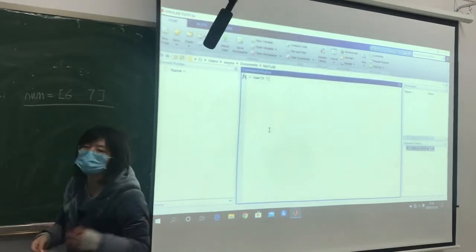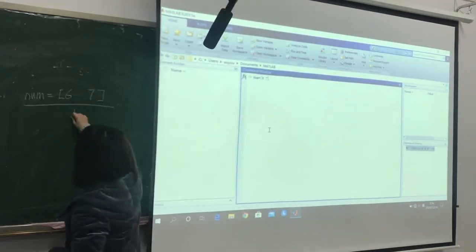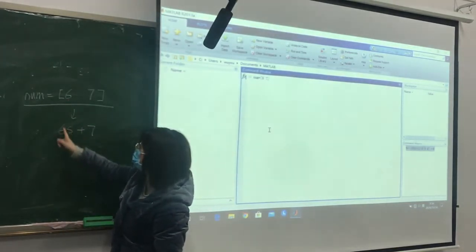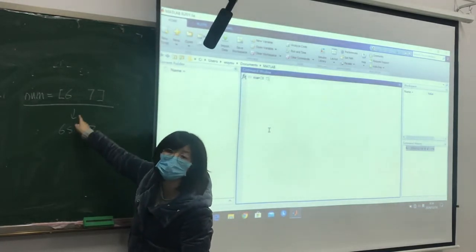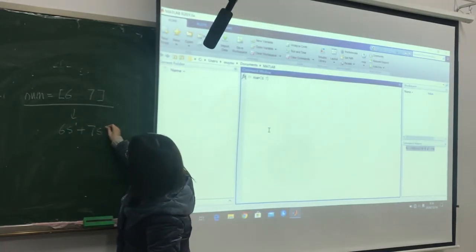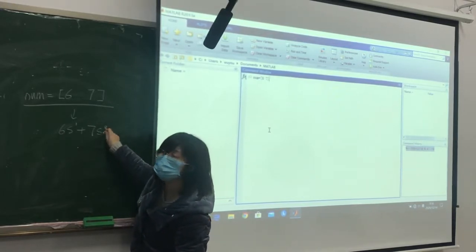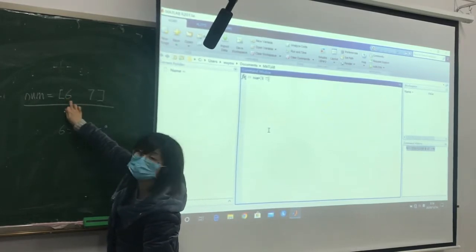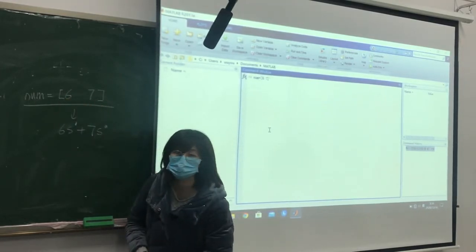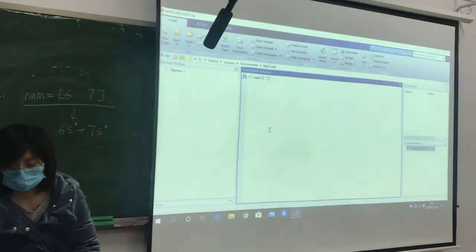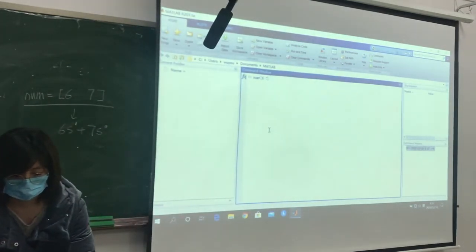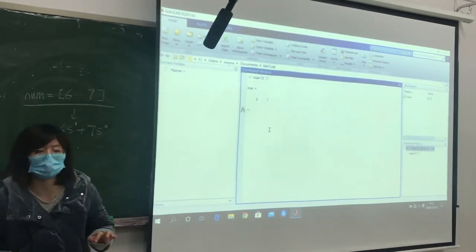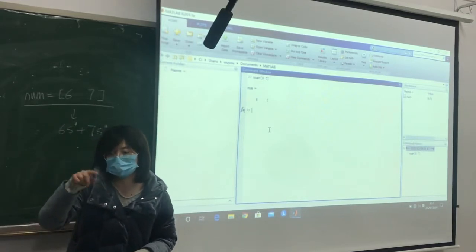This matrix means that for your transfer function, the numerator is 6 and 7, because 6 is the coefficient for s order 1, and 7 is for s order 0. So according to the order numbers 1, 0, you write 6 first and then 7. Then click enter, and it shows the type, just a matrix, and the value is 6, 7.